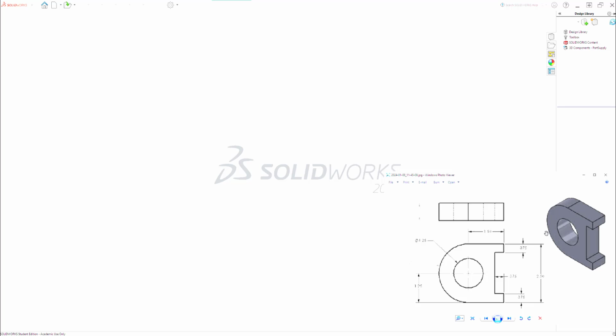As you can see, if we were to look at this isometric object and sketch out the front face, this is the front face that you would see, the shape. Now why would that be the front face? The front face is typically the most complex shape, or it's the longest shape. Those are the two general rules that focus on how you select the front of an object shape.